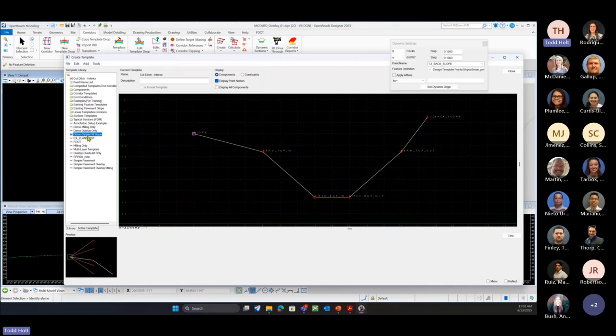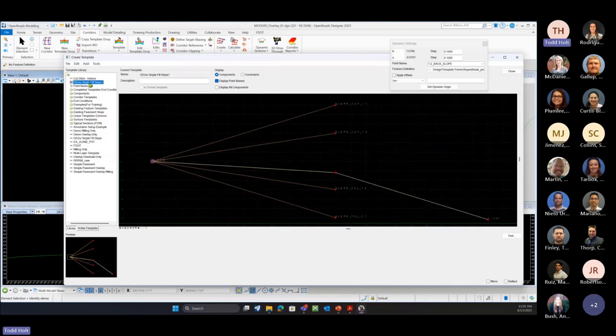All right, so we have our demo for a simple slope. I'm just going to right click on this and copy, then paste that demo slope, make that my active, and we can rename this. So maybe this is our demo simple slope, but with the ditch now. All right, so we have that solution in there.